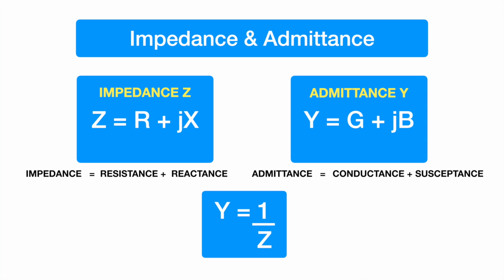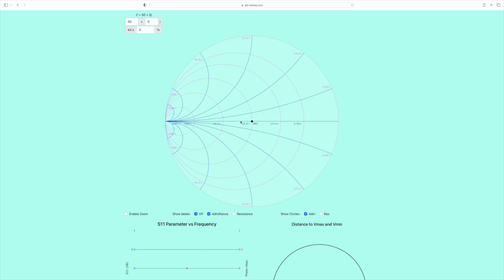And just as impedance has a real and an imaginary part, so does admittance. Admittance has a real part called conductance, and an imaginary part called susceptance. And what you're seeing here, these pink circles, are circles of constant conductance. Admittance is sometimes useful to look at situations from this opposite perspective. Why I'm showing you this now is because this is a different set of circles going the opposite way. You remember the circles of constant resistance go around like this. Well, these are going round the other way. They're emanating from the other end, if you like.